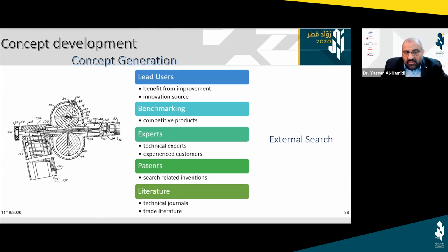This design uses the accumulation of rotational kinetic energy in these two flywheels, which is suddenly converted into translational energy by a friction clutch. The energy here, as you can see, is delivered to the nail with a single impact pin. So you see this pin here.